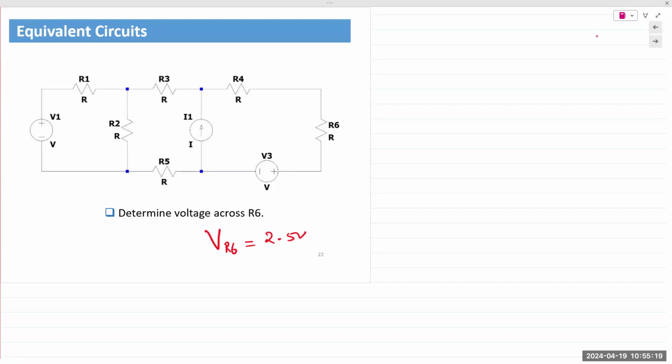So what do you do? You analyze the circuit, either node voltage analysis, mesh current analysis, or superposition. You find the value of R6, right? Use NVA, or MCA, or SP to determine R6. Then you find the value doesn't fit. Let's say you chose R6 as 50 ohms.